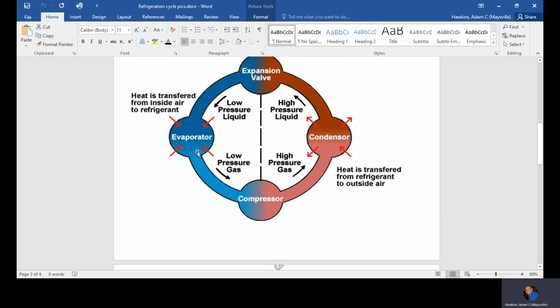In a residential split system, just regular AC, you're looking at that coil being above freezing. Usually, you're going to run about a 40-degree coil. Now, what does that mean? Does that mean the surface of the coil is actually 40 degrees? No, not exactly. We're referring to saturation temperature.